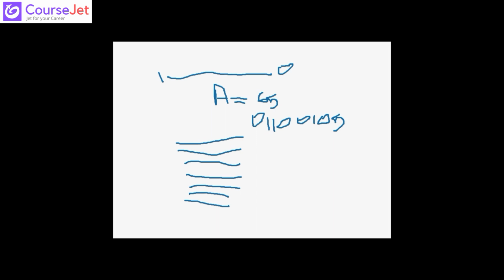So which is better, parallel communication or serial communication, completely depends on our requirement. Basically, when you are doing small distance communication, you'll go for parallel communication, because the cost will be less as the length of the wire will be less, and it is very easy to detect errors in small length. You'll go for parallel communication, like a printer. But when you have long distance communication, you will go for serial communication. You will be sending 1 bit by 1 bit.